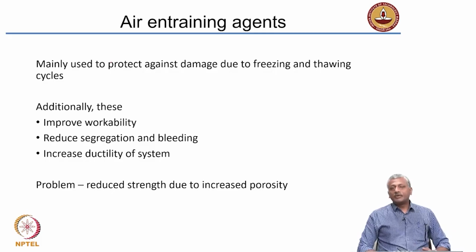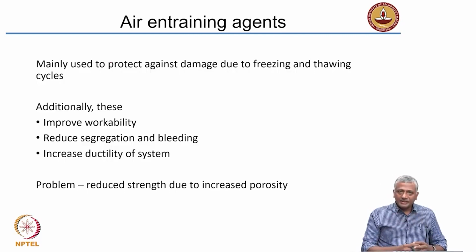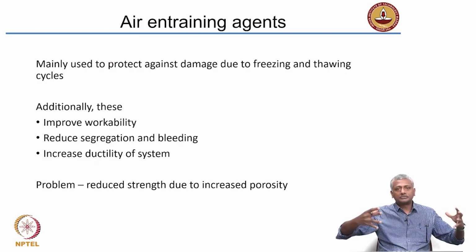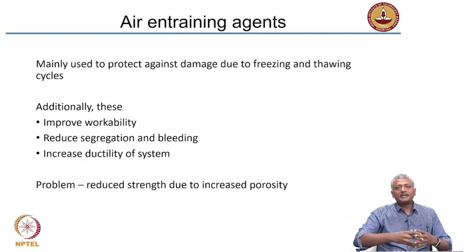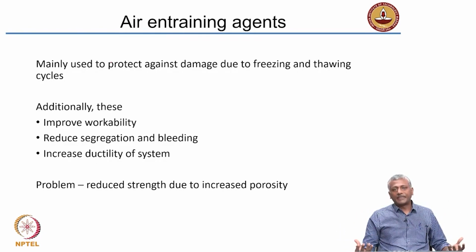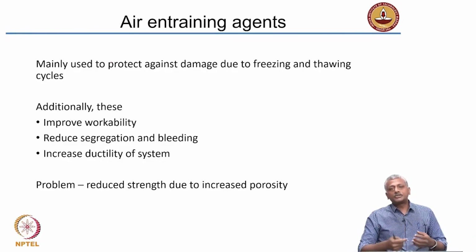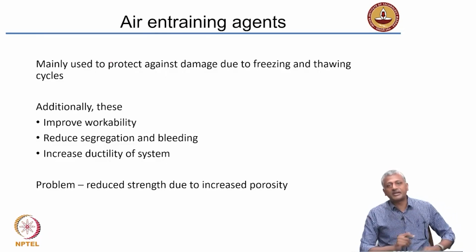Sometimes in very cold areas, you may get temperature fluctuations that can cause the water inside the concrete to freeze, and then a subsequent increase in temperature causes it to thaw. So, it freezes to ice and then it changes back to water. Interestingly, for water, when it transforms to ice, it leads to an expansion in volume. Very few materials exhibit this behavior, right?